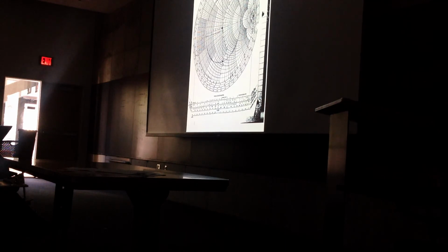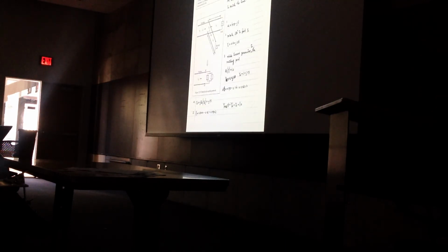So if we go back to my chart, here it tells you that is 0.344, that's the final destination, and your short circuit location corresponds to 0.25 lambda.